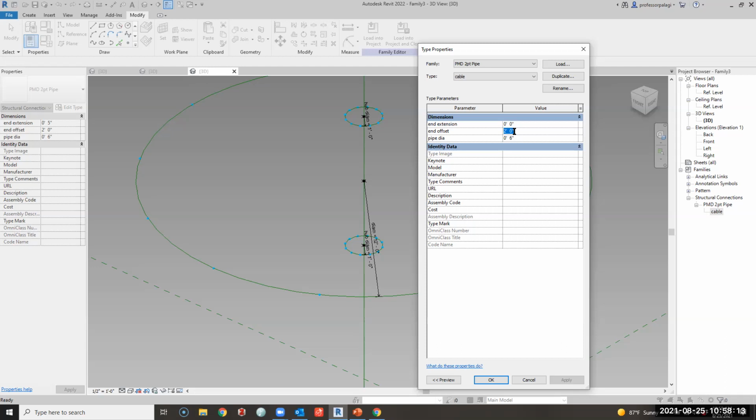You know, when we have 2 pieces of wood meeting each other, the structural integrity of the beam and let's say a truss, you know, you have truss members, there's a thickness to that 2x4. The structural line is a center line here and a center line here and a center line there. Those points are what's important, even though the wood's not going all the way to there, right? So just that idea that the structural line is different than the object, right? So I'm going to leave that at 2 feet right now. We can change it later.